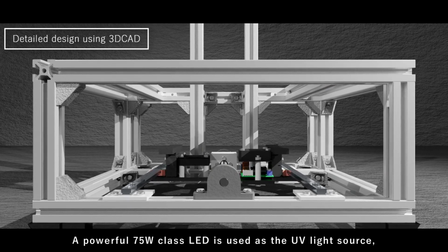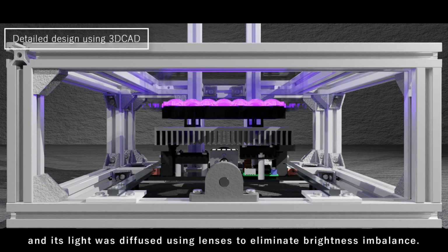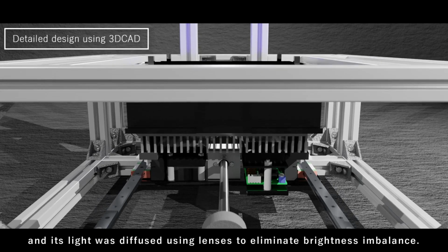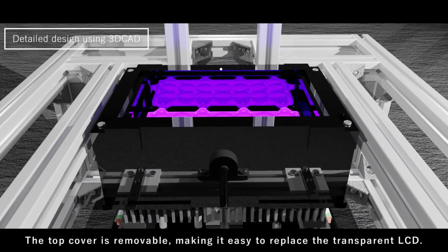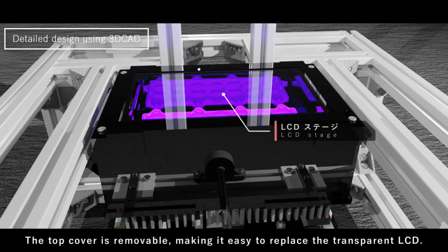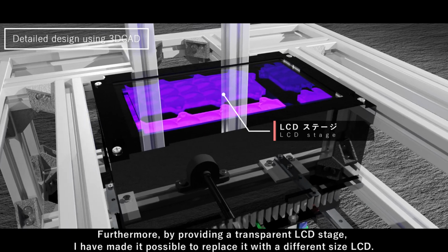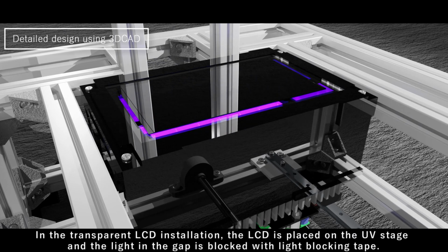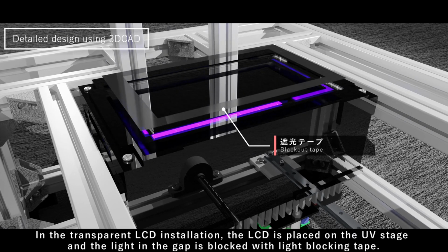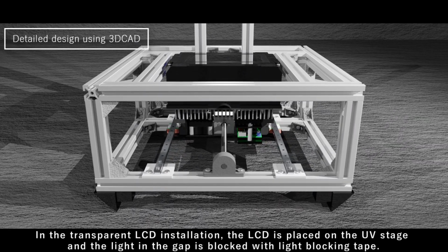A powerful 75-watt class LED is used as the UV light source, and its light was diffused using lenses to eliminate brightness imbalance. The top cover is removable, making it easy to replace the transparent LCD. Furthermore, by providing a transparent LCD stage, I have made it possible to replace it with a different size LCD. In the transparent LCD installation, the LCD is placed on the UV stage and the light in the gap is blocked with light blocking tape.